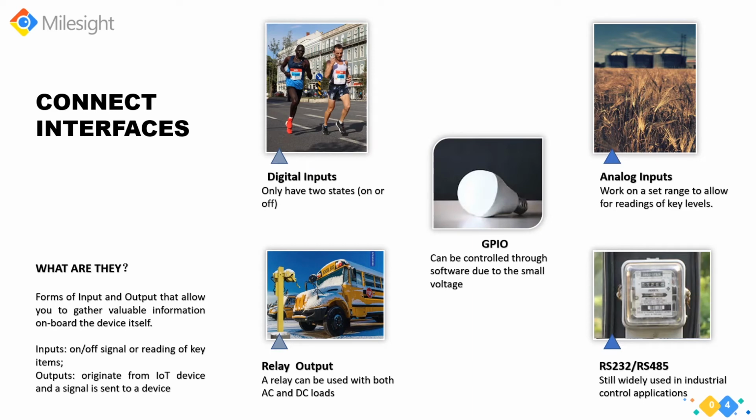You can also find POS, point of sale terminals, and metering instruments, and those kinds of devices can be connected to the RS-485 interface. And the networks defined by the field bus, like Modbus, use this interface as well. So now we understand the most popular ports or interfaces in the IoT world.